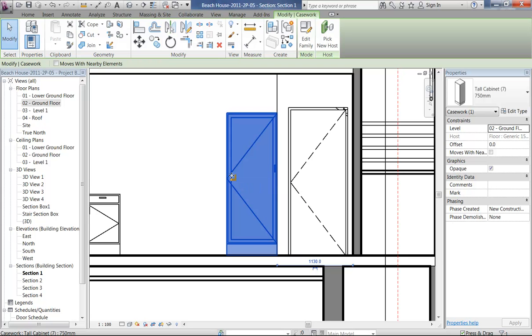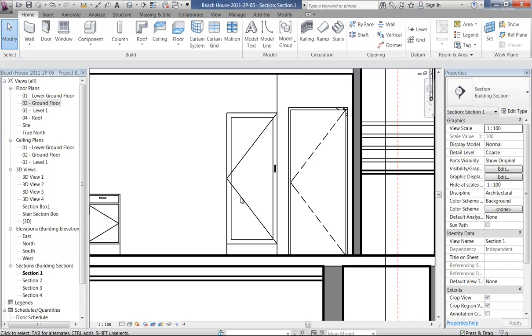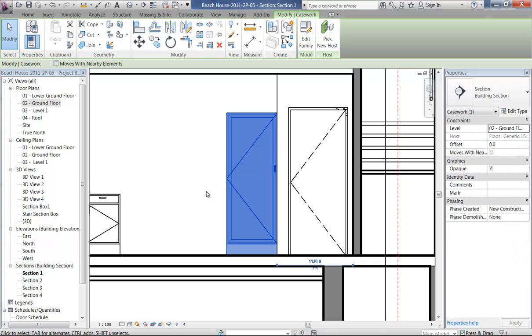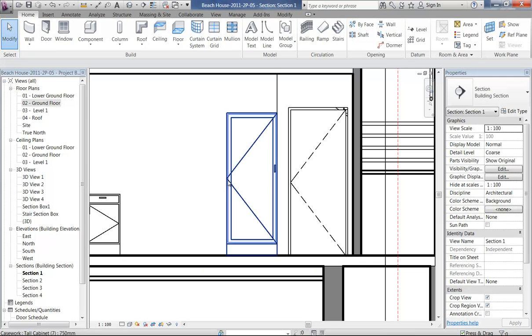I like this line here. So that line shows the door opening direction, and that's called a chevron. So which way do you think that would open? Well, that point would be the hinge point. That's actually right according to the Australian standard, but it's not the way everyone does it. Most people do it the opposite way.